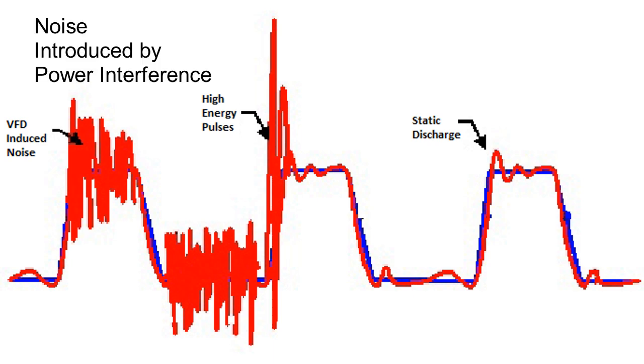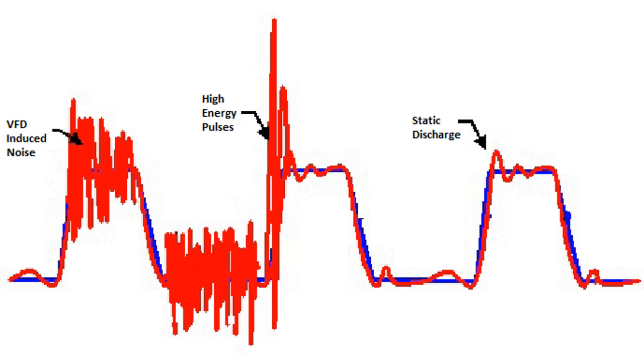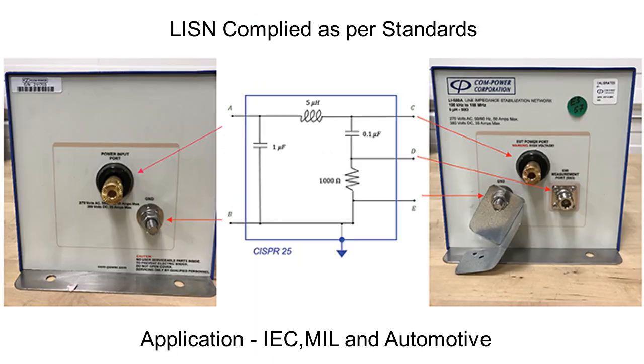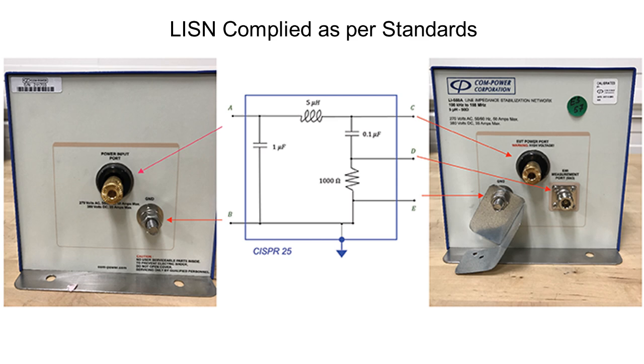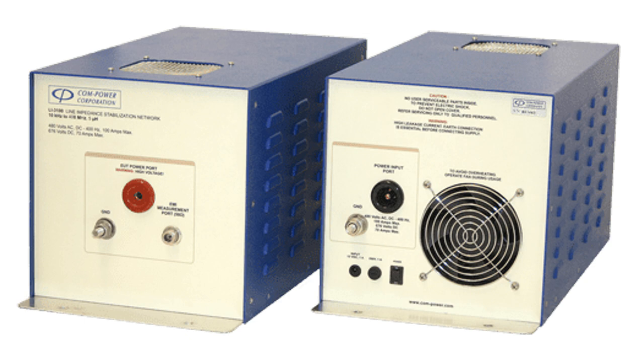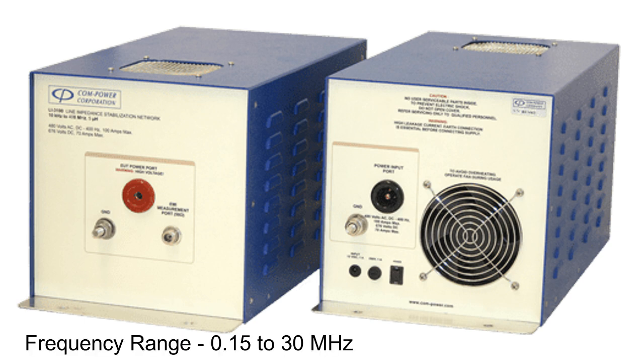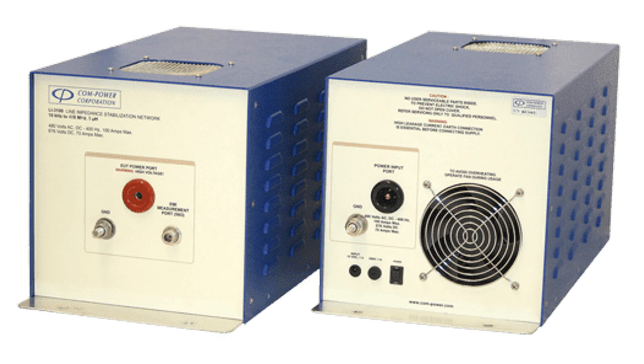Any noise currents from the power system net that were to enter the product's AC power cord would add to the conducted emissions from the device. Since we are only interested in the conducted emissions that emanate from the device under test, it is important that the LISN prevent noise from the power system net from entering the product's AC power cord. The LISN must satisfy both of these objectives over the entire conducted emissions frequency range, 450 kHz to 30 MHz for FCC regulations and 150 kHz to 30 MHz for CISPR 22 regulations.